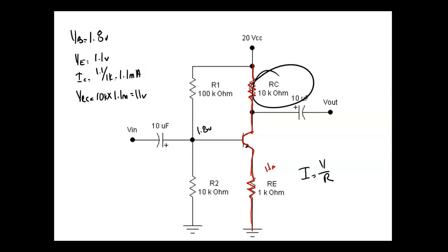What's the function of resistors besides creating what? Creating heat, dropping the voltage and creating heat. So that's what you learn. But you learn how to calculate parallel circuits, series circuits. You probably did a lot more complicated series-parallel circuits than this guy. So one side we got two, so we're treating them like series resistors. The only thing that we got to know is what sets the voltage right there. Well, what sets the voltage right there is whatever I calculate across R2.